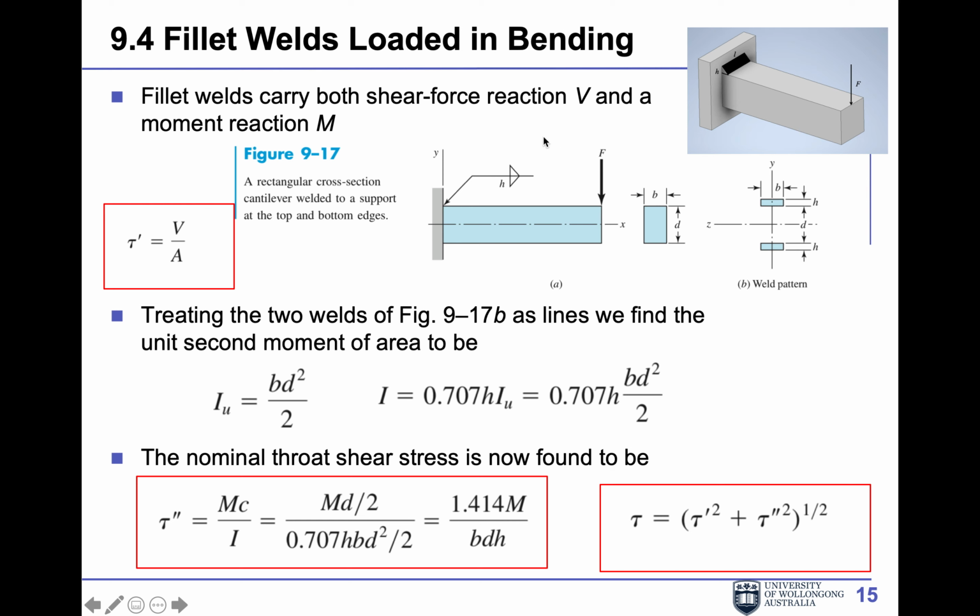this one, where it's in bending, you have to get tau 1 is V over A, tau 2 is Mc over I. So here I is again another thing. You have a table to look at, but if it's not in the table, you then have to derive it by yourself. So it can be a very, very tedious question if we ask the question slightly differently.